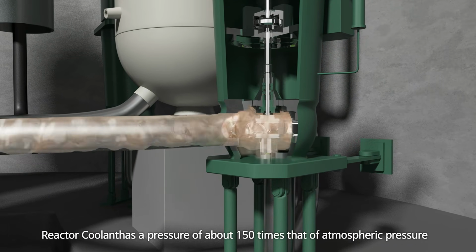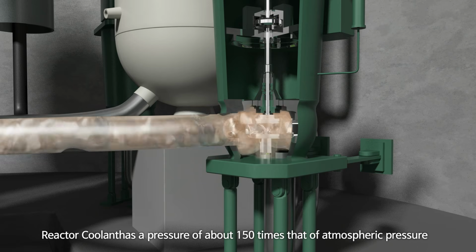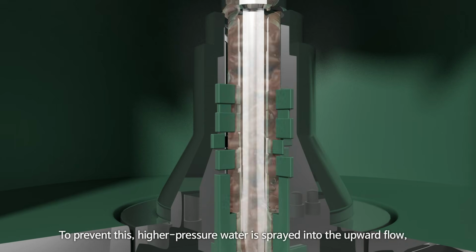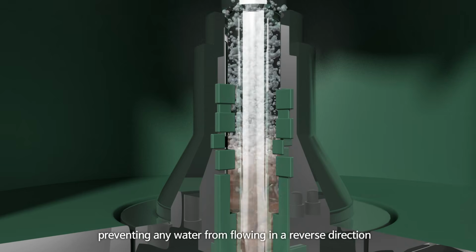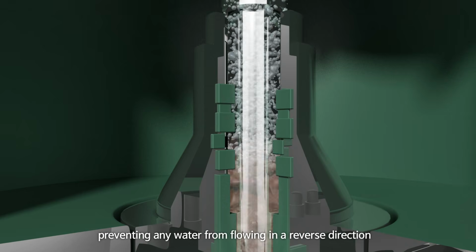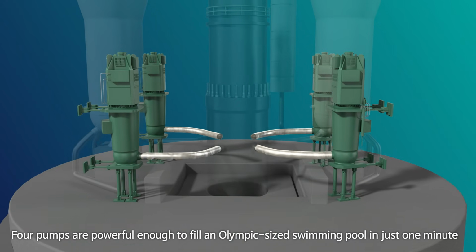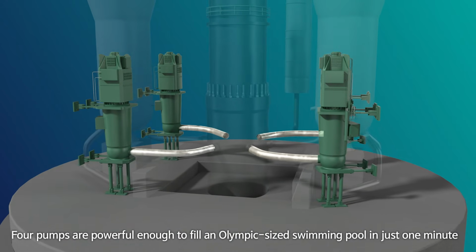Reactor coolant has a pressure of about 150 times that of atmospheric pressure. Water tends to flow backward through the narrow gaps between machineries. To prevent this, higher pressure water is sprayed into the upward flow, preventing any water from flowing in a reverse direction. 4 pumps are powerful enough to fill an Olympic-sized swimming pool in just 1 minute.